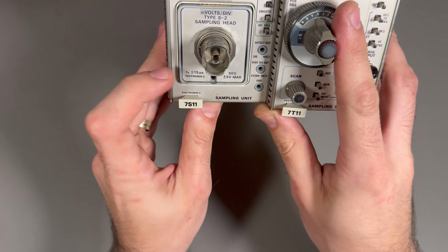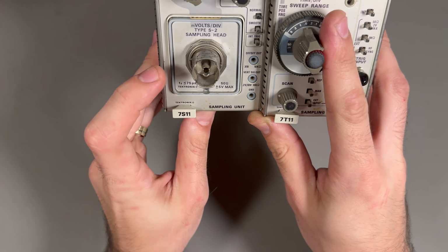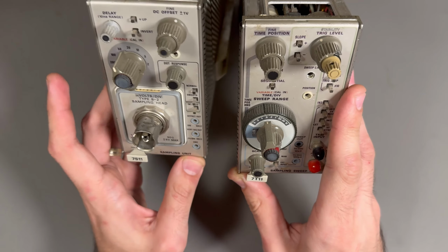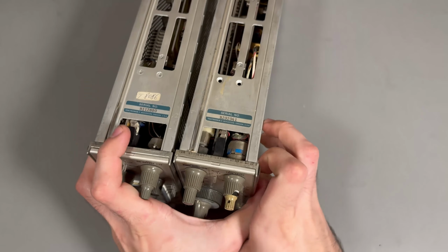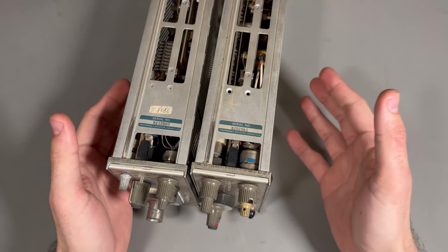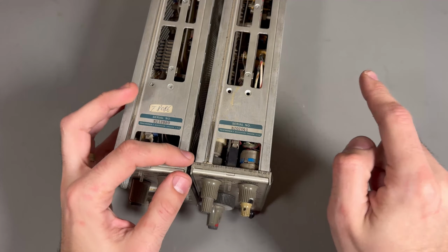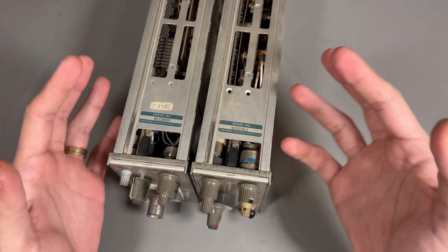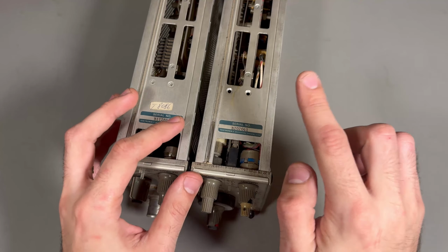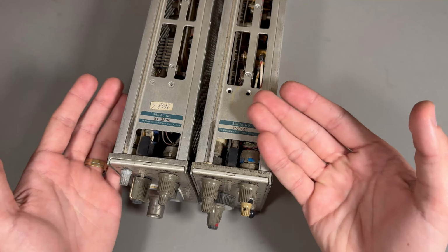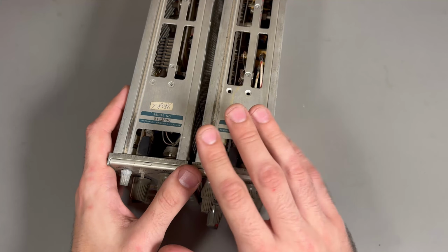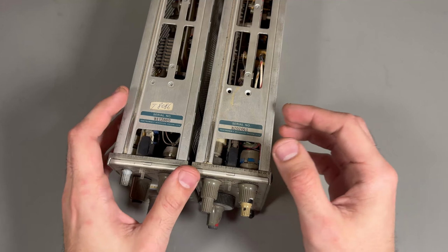This is 75 picoseconds or less rise time, but only if you have a repeating signal. So for a single shot event, you're out of luck. You can't use these. These rely on acquiring a signal at various points in time, provided the signal stays sort of constant, and reconstructing the waveform out of basically points. So this is analog sampling, basically.